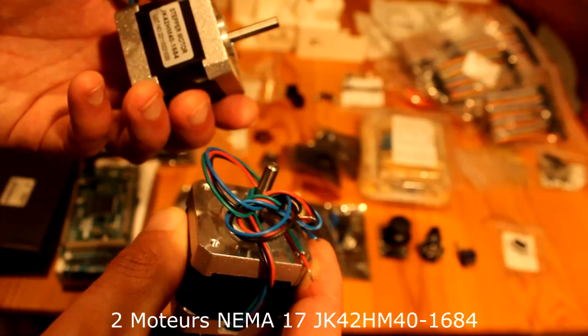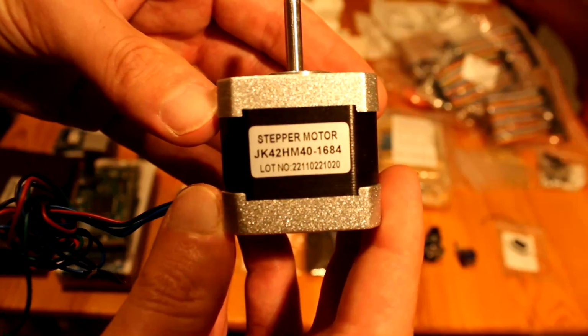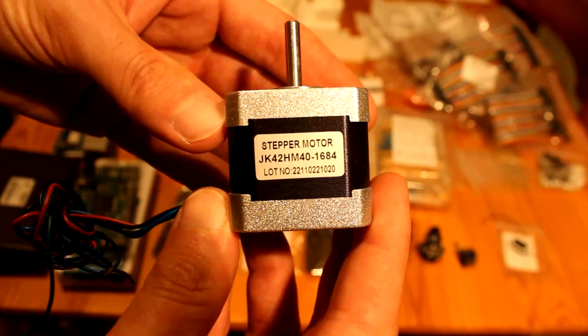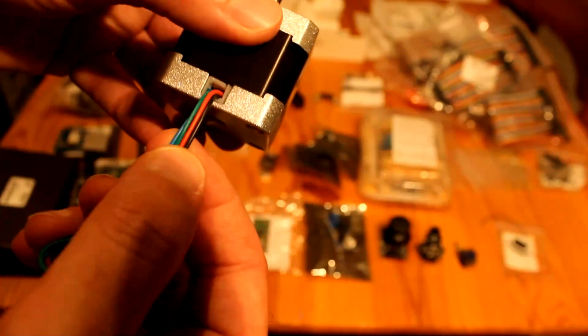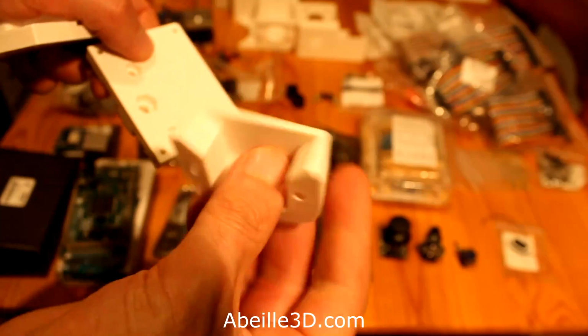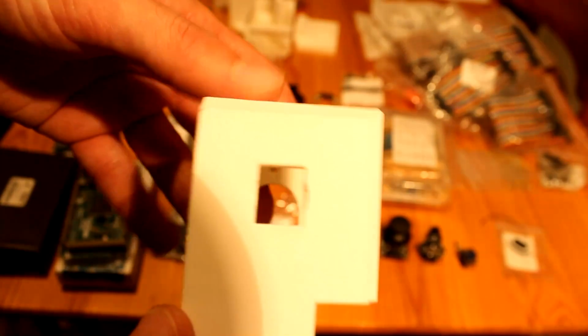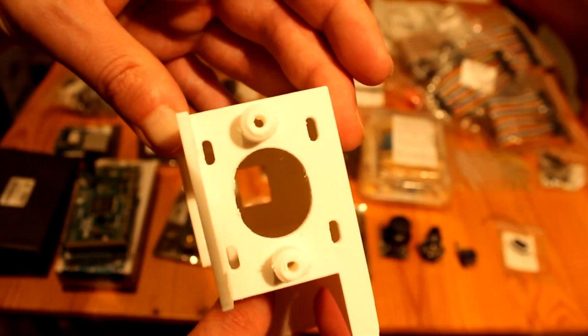2 NEMA 17 motors, you can see the reference right over here. These are 4 wire motors, 400 steps and 1.68 amperes per wire. The 3D printed motor holders are very good quality and very good price, printed on ebay3d.com. Found it on the OnStep website. These are already existing models that have been modified by Mr Khairey Nouhe to have a rectangular hole for the RJ45 port. You're going to find the Thingiverse addresses at the end of this part.